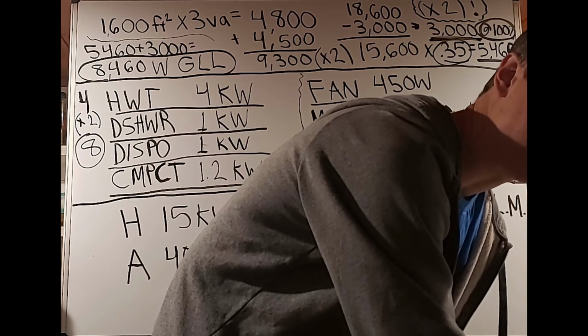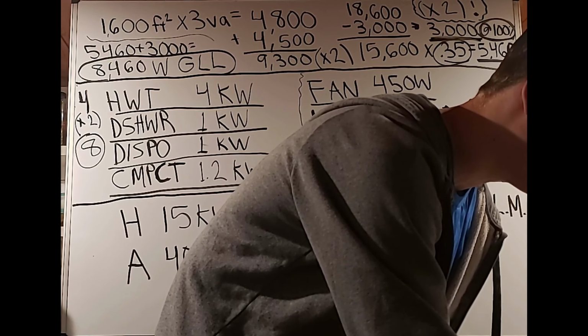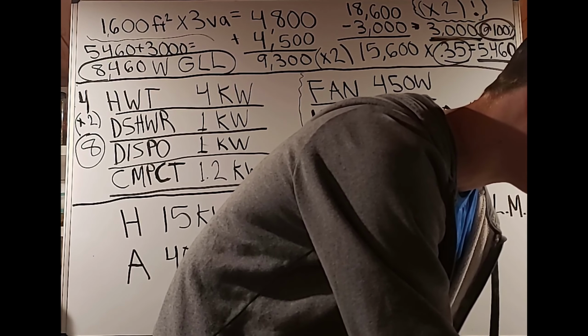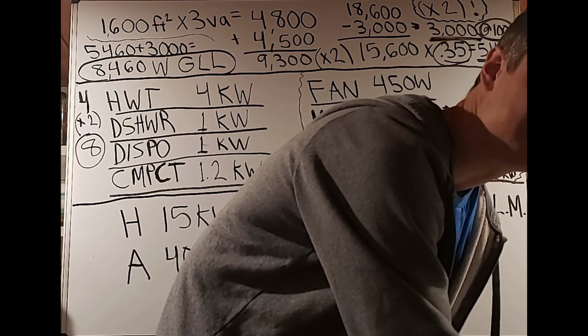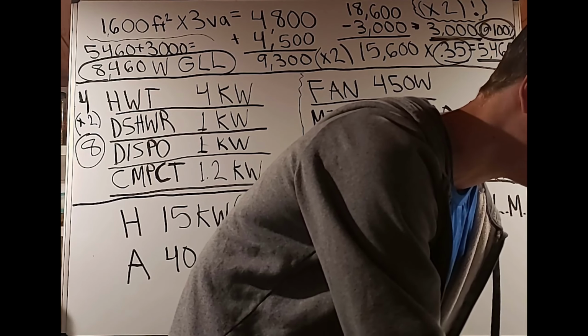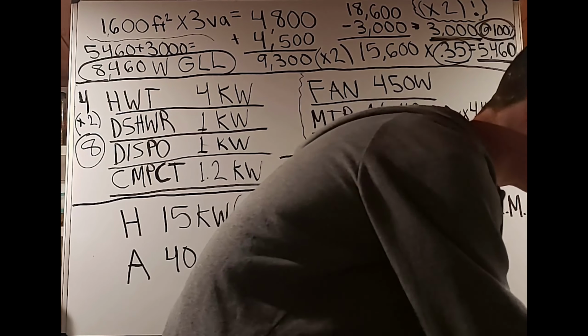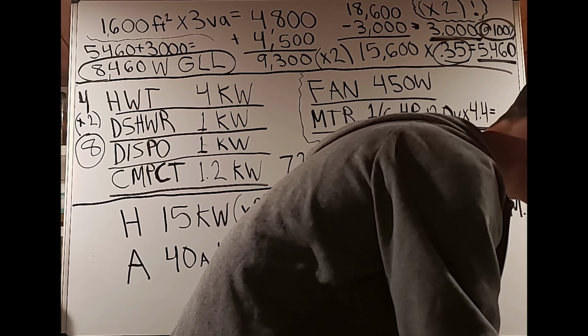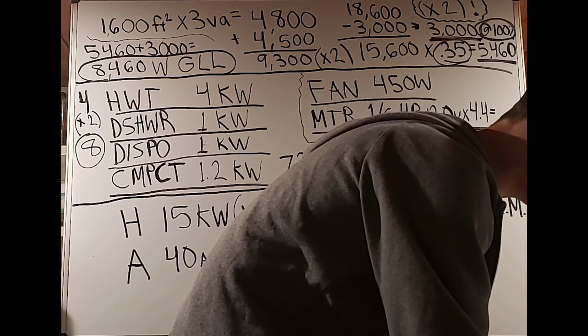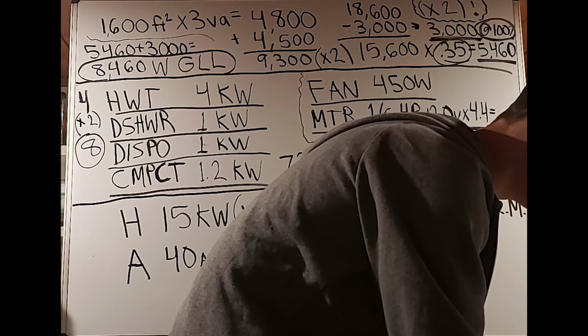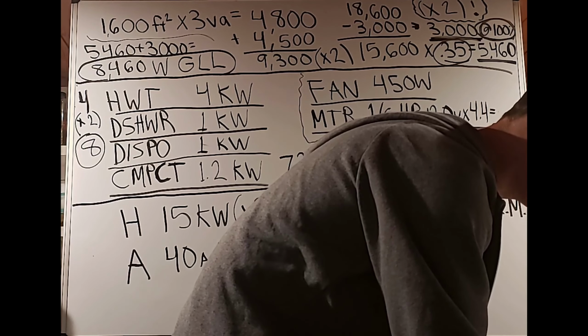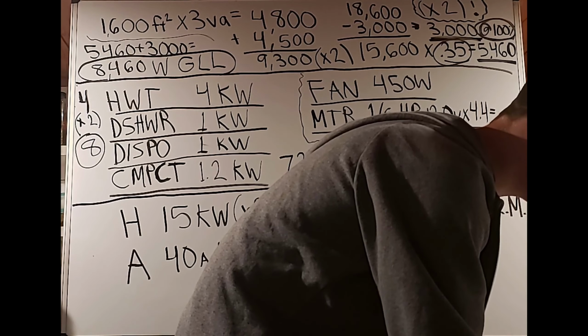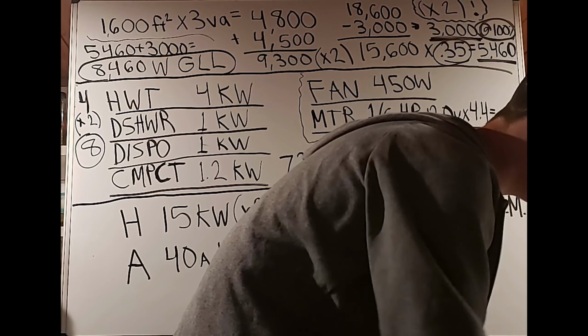That's here in the load calculations. So when you're calculating all your numbers, when you're doing all your math, you can see the voltages you're going to be using. I already explained this in that first residential load calculation video. It's quite a mouthful, so just make sure you're aware of that. As you see, we have 120 volts, 240 volts, we can also use 208, 347, 480, and 600. We're not using anything else.